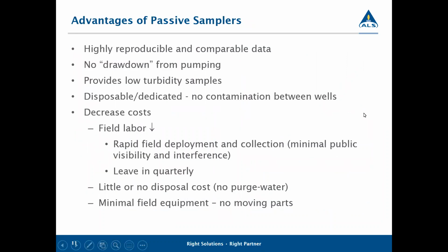So what are some of the advantages of passive sampling? We touched on some of them already, and I'm sure everyone on here knows that highly reproducible, comparable data is always a plus when you know that you can rely on that. I've mentioned this, you don't get the drawdown that you get from pumping. So you're not pulling in water from different areas around the well. You're actually getting what's sitting in the well.